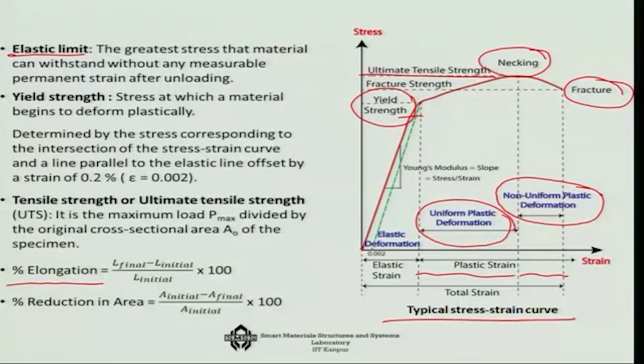So, this is a typical stress strain curve for a ductile material. How will it look for a brittle material? I can draw it here in a small qualitative manner. Suppose the stress is denoted by sigma and strain by epsilon. If I draw the sigma epsilon curve for a brittle material, it is just one single line, maybe with some point of nonlinearity, but that is it, and then it sharply fails. That means it will not show any plastic strain or plastic deformation. That is what generally happens for a brittle material.